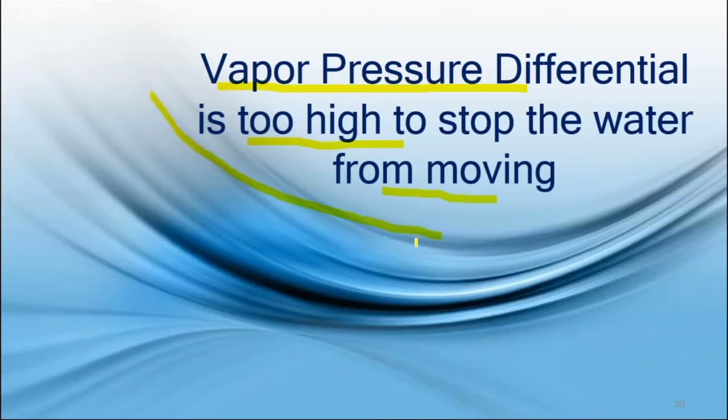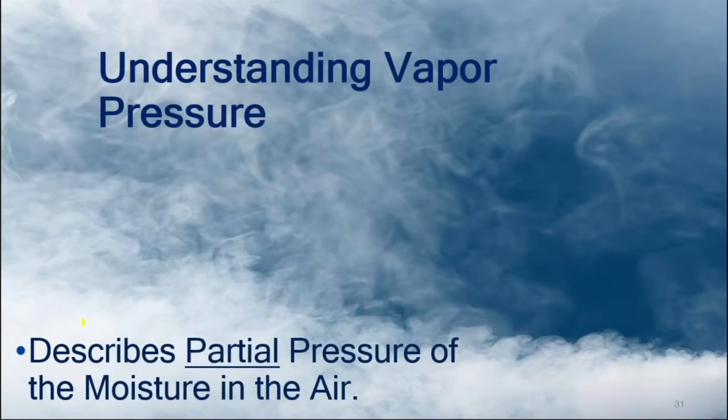So if we have a curtain of air, we're moving it across some opening. That curtain is usually 2 inches thick or something like that. At a velocity of 3,000–4,000 feet per minute, we can get some sort of a differential. It's significant, but not significant enough to overcome vapor pressure. So let's first understand vapor pressure. How significant is this pressure that we're dealing with?